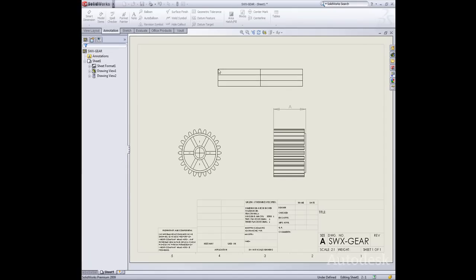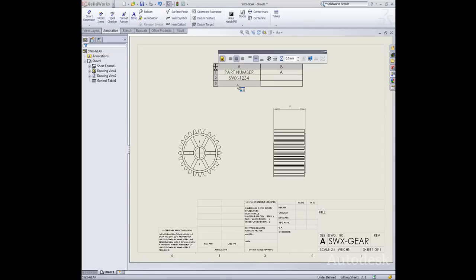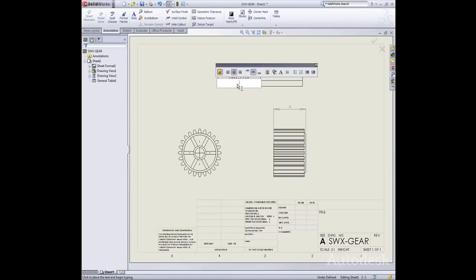And again, remember this file configurations in SolidWorks. All of these various lengths are kept in a single file format. So from a data management or a bill of materials standpoint, in data management, that becomes a real problem because everything references back to a single file. So there's a lot of challenges with that from bill of material management, from a data management standpoint, or even consumption down to ERP and MRP systems for purchasing and procurement. So it's very important that we look at how Vault Manufacturing can address this anomaly with SolidWorks files.